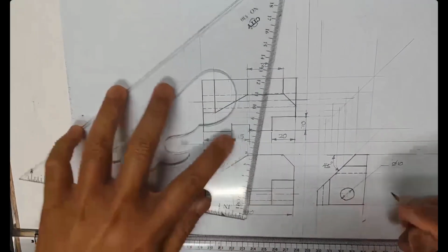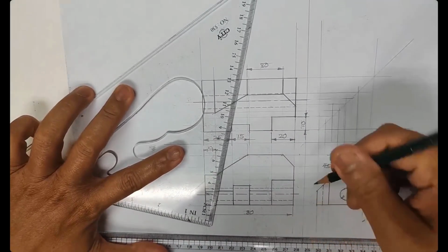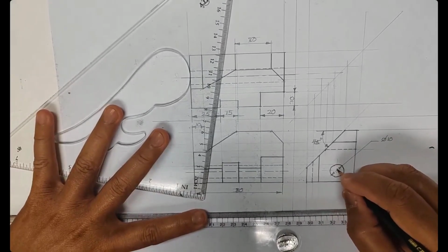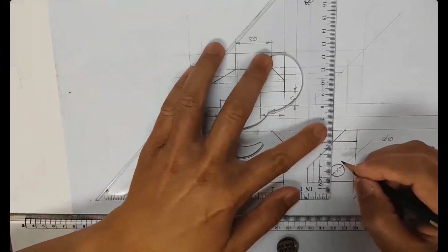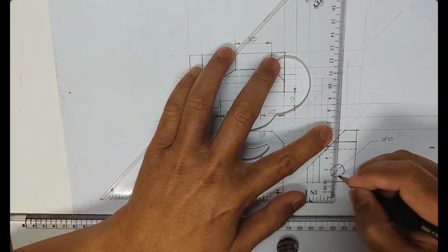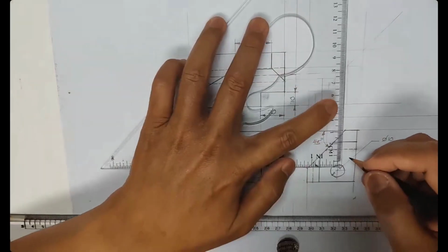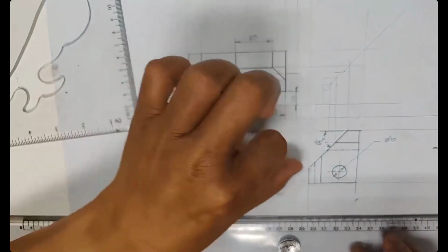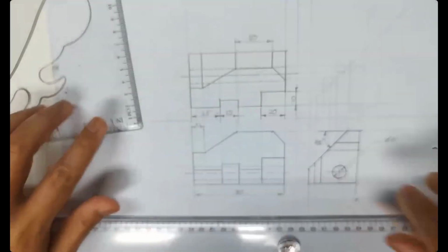Okay, remember guys, for the center point we have a tick. I need to be quick. You're not doing it by hand like I show you. You have to have a tick here. Do it by ruler. Okay, tick, and we only have a center mark. Center mark like this, center mark like that, and you cut like this, right? So you have to see. Remember this one, I already have hidden line and center line. So here, hidden line and center line.